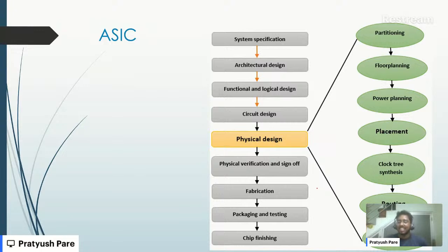Because STA is static timing analysis, and this is analysis of the static logics. Like, you will have this logic change in this clock cycle, and you need to make sure that logic does not change when I am not expecting it to change. So you have some clock frequencies, some specifications. So in STA, you have two concepts, setup and hold. Setup is sensitive to frequencies, hold is sensitive to logic. Means setup also has the logic components, but yeah.